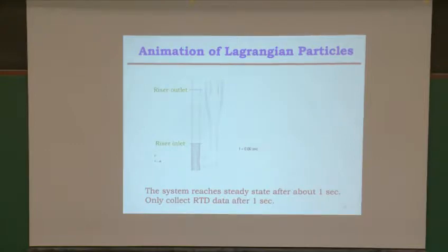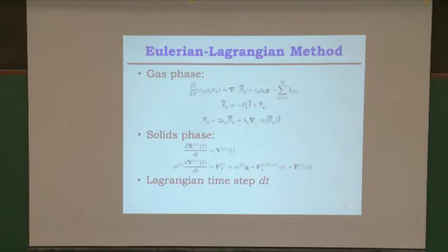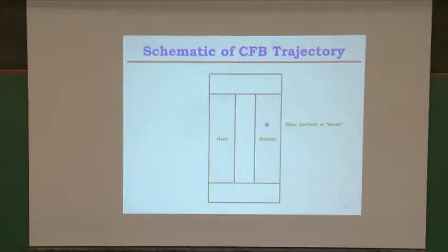Are these particles only to track the statistics, or are you actually doing a two-fluid simulation? Well, it's actually a Eulerian-Lagrangian type simulation. We're using Eulerian equations along with solid phase equations, but here we're using the collision model that I showed that we derived. So we're keeping track of where those particles are going when they travel in the system.